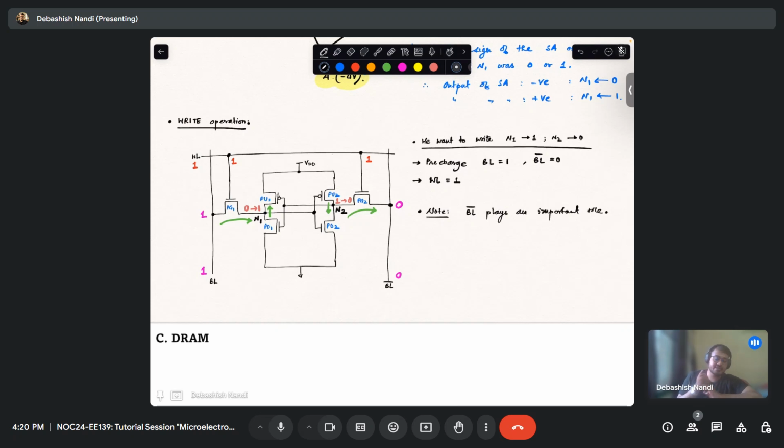So this is very basics. There are some advanced concepts and nitty-gritties involved, or the trade-offs involved when reading and writing, and how the capacitances come into picture that determines the glitches in the timing diagram, or in the hold state of the SRAM, how the so-called butterfly curve is obtained, and that helps to hold the value.